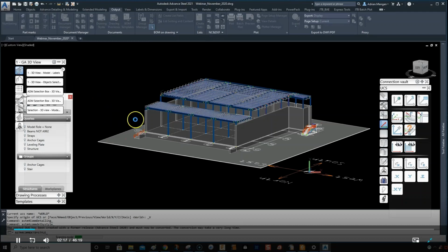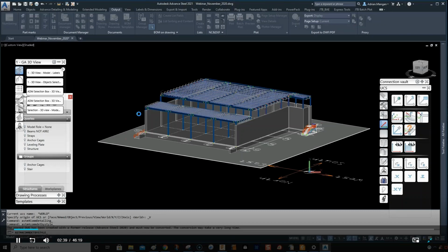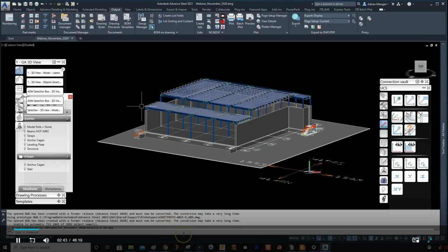Now, I haven't changed the scale in there. The scale, I believe, in that box in the drawing style was 3/4, which is rather large for a 3D view. It should be down like an 1/8 or a 1/4 or 1/16, depending on what size your model is. So this is just generating here.